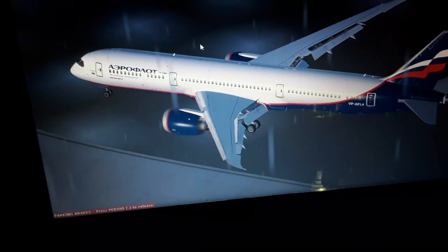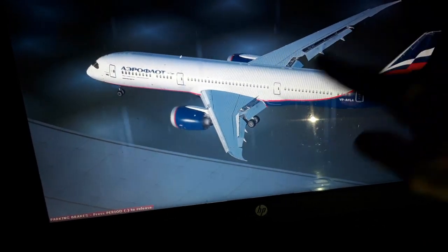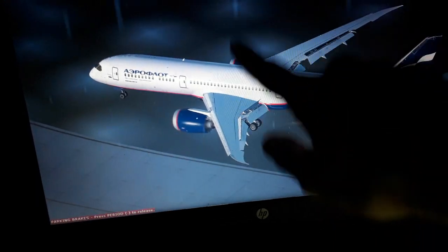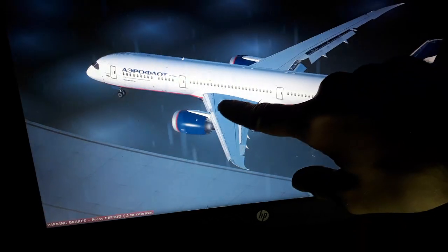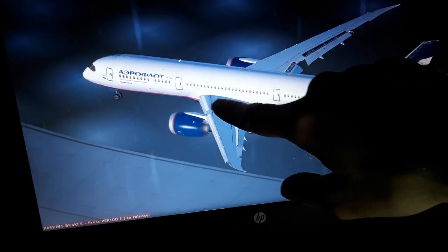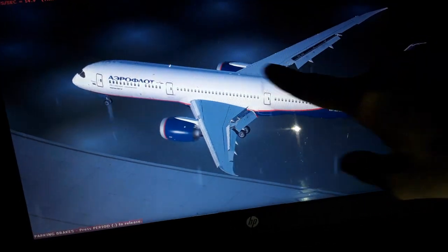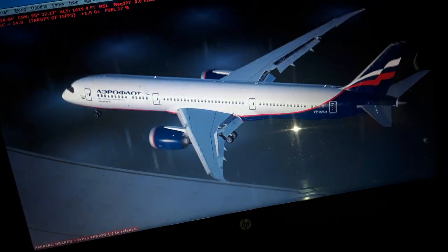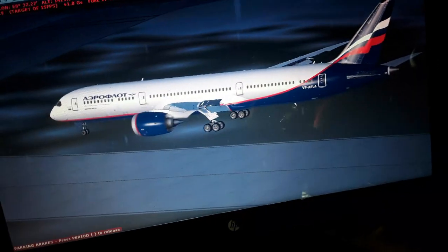We have also the lateral axis from wingtip to wingtip and the vertical axis through the center of gravity. This is also the position where the stall will begin as the aircraft flies. For a given angle of attack and airspeed, the airflow of the air mass will become detached from the top surface of the wing. So we need to avoid the stall during the flight. We have also the wings.